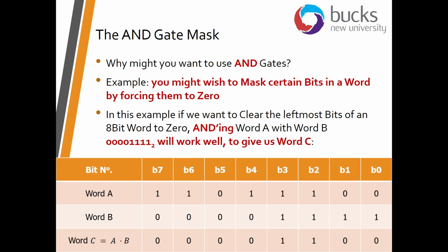Now what that means is, as we know, for a logical AND operation, where you have zeros, the only thing you're going to get on the output is 0. So you can see that word A, when put through this logical operation with word B as a mask, has its 4 leftmost bits all set to 0, so we can only get zeros on the outside.